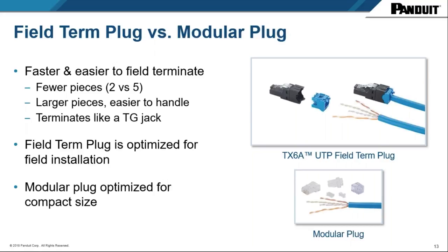So yes, it is possible to use a modular plug to terminate in the field. It is not nearly as easy to do on the top of a ladder in the typical field installation environment. So again, the field term plug is optimized for that installation in the field where you want speed and you want ease of handling.